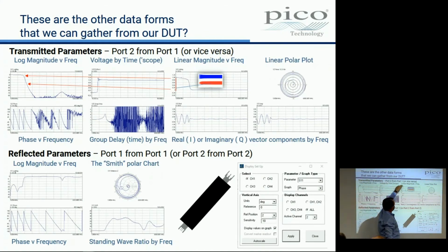This is what happens for this DUT. The linear gain goes on, it falls away gradually, and then it comes to, what's this? It's about 700 megahertz or so, and it goes off a cliff. And so that is our equivalent to our scope network analyzer. Now, it doesn't tell us that much because we can't see anything along here. There's nothing going on out to 6 gigahertz, so that plot is of limited usefulness to us in the context of a VNA.